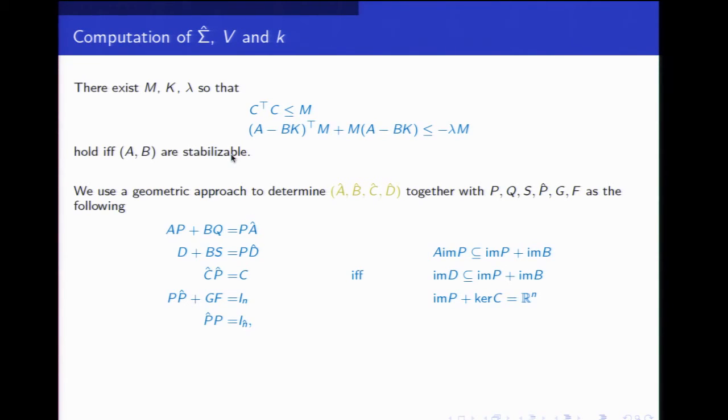So you need to know the dimensions to begin with, right? You start from the lowest dimension, and then you see if the condition is satisfied. If it's not, then you add another column, and then you check, yeah? Until P equals identity. Of course, in the best case, you don't want n hat to be equal to n, because that's the whole point of the abstraction. So n hat hopefully should be less than n, so that you benefit from the abstraction. But I'm sure there are systems where P will actually hit the full dimensionality, in the sense that you cannot get rid of any of the state variables in your concrete system. And because it's an if and only if result, there is no other way. And this is the interface, how to lift the controller we designed for the abstraction to a controller for the concrete system. That takes care of the lifting or the refinement of the controller, which I explained.